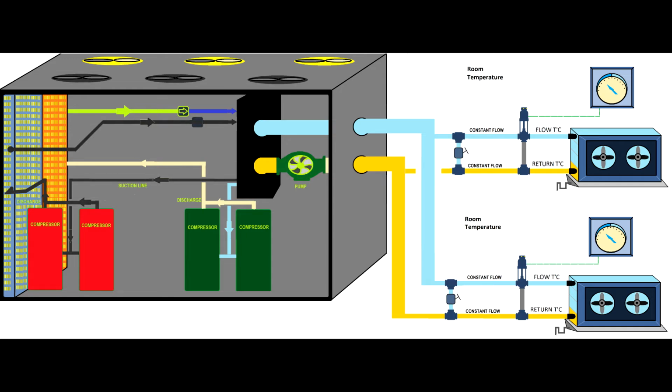So if someone repairs your system in winter and you say, okay, I did a great job, you don't have a good heat load in the building, and you will not know until the summer comes that half of your system is damaged. And when the summer comes and the heat load increases a little bit, the second group of compressors will try to start, but they won't be there, they're not working.